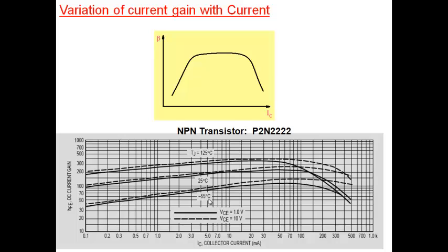If you're telling a customer that I guarantee an input resistance of 1K. Well, if he measures in summer, it's okay. If he measures in winter, if it's not 1K, he's going to complain. So you have to keep in mind how the beta is varying. And when you tell somebody that input resistance is going to be larger than 1K, then you have to make sure that at minus 55 degrees Celsius also it is larger than 1K. Yeah. So when you make practical circuits, you have to take these things into account. Your circuits are supposed to work not just at room temperature, they're supposed to work at a range of temperature here. So you have to take these variations into account here.